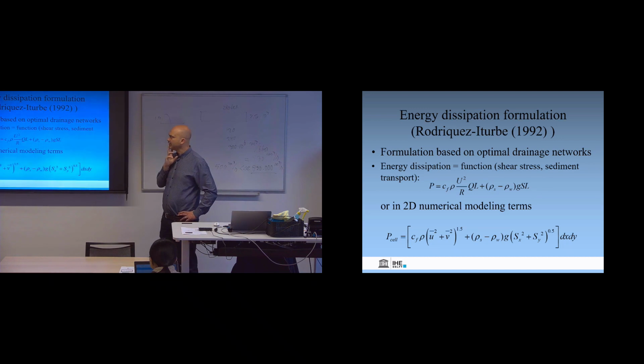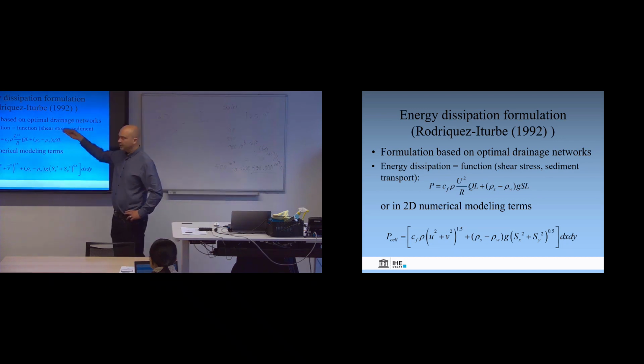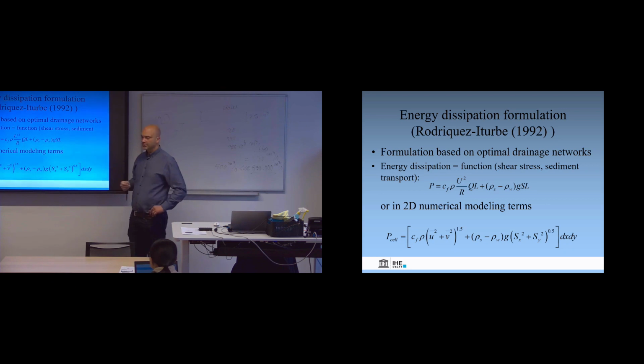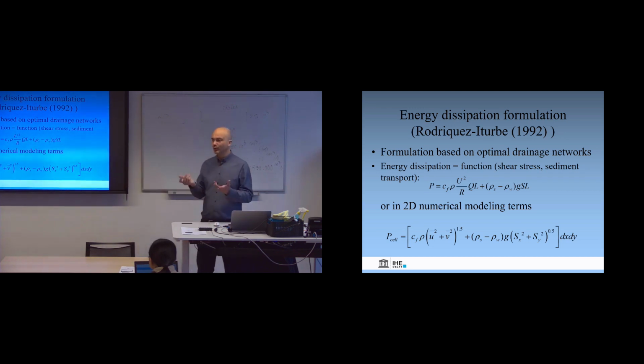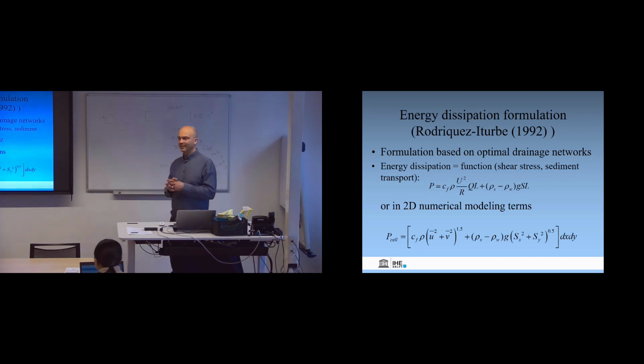And what is energy dissipation? That's a function of shear stress and sediment transport. The more shear stress you have, the more friction there is, and more sediment transport. Also, it costs energy for the basin. And what he says is, well, it's a lazy system. It needs to work, like people. But it's a lazy system because it develops towards a state of less and less energy dissipation. So it organizes itself in such a way that it dissipates less energy.